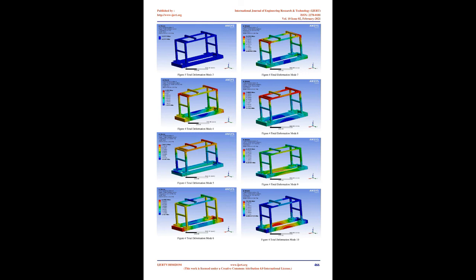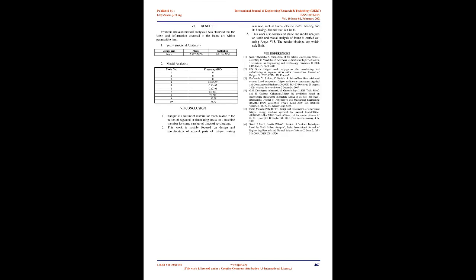Vibration absorbers. The term vibration absorber is used for passive devices attached to the vibrating structure. Such devices are made up of masses, springs, and dampers. From a control point of view, vibration absorbers can be considered as passive controllers. The term passive is used loosely here, meaning that the controller can be constructed using masses, springs, and dampers. For such controllers, stability is not an issue, since the closed-loop system is also a passive one.